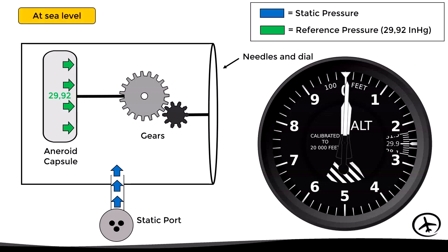In this case, if the aircraft is at sea level, the static pressure inside the case will be roughly equal to the pressure inside the aneroid capsule. In this situation, the aneroid capsule will be contracted and the needles will indicate 0 feet.